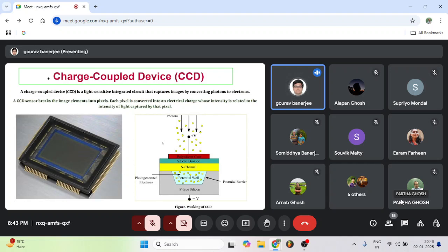So this is a CCD image. Whatever detectors we are using in our observatory are CCDs, and all the modern, new age detectors are CMOS detectors. It works based on the photoelectric effect, meaning when light falls on a metal surface, it emits an electron. On this side you see a chip. This is the actual photon gathering area. These are the pins connected to the electronics, and this side is the basic structure of a CCD pixel.